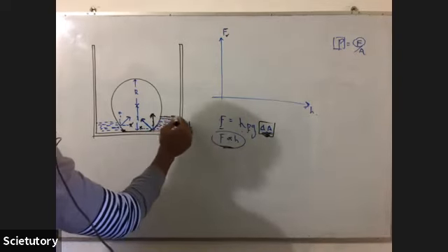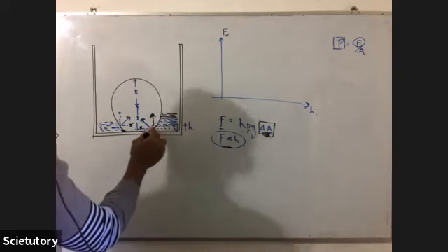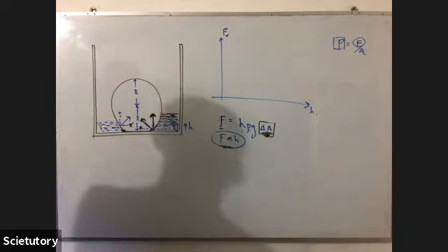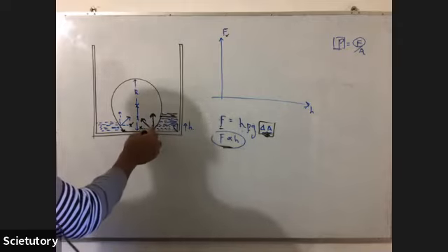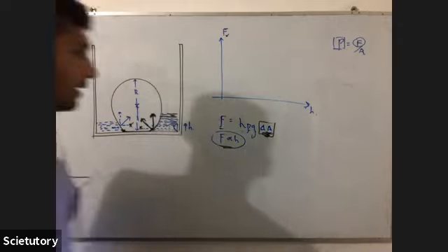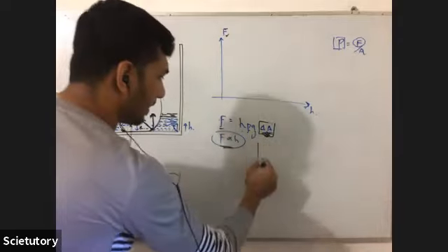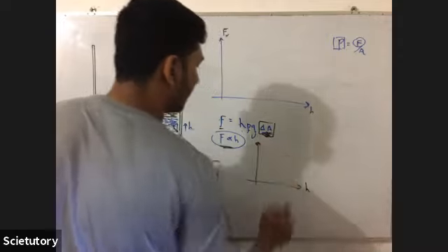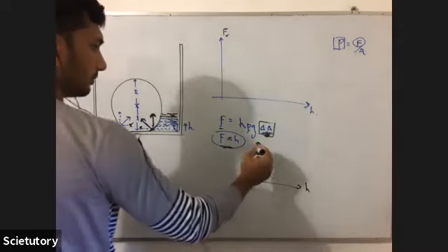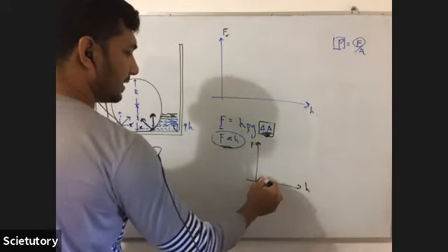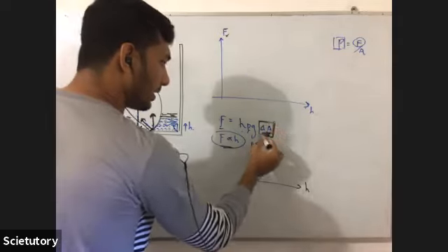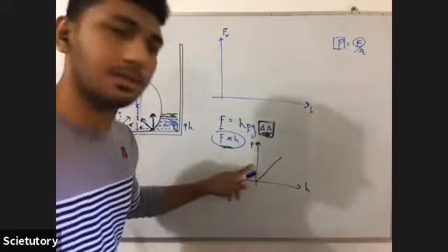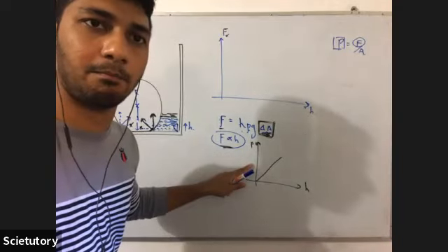Okay, when you keep on increasing the H, this force will increase and this vertical component will also increase. So when you draw a graph for that particular surface area, force on that particular surface area with H, what will happen? It will linearly increase with H, no? Because we are considering only that part, small part. For that small part, if you draw like this, you will get this kind of a diagram.